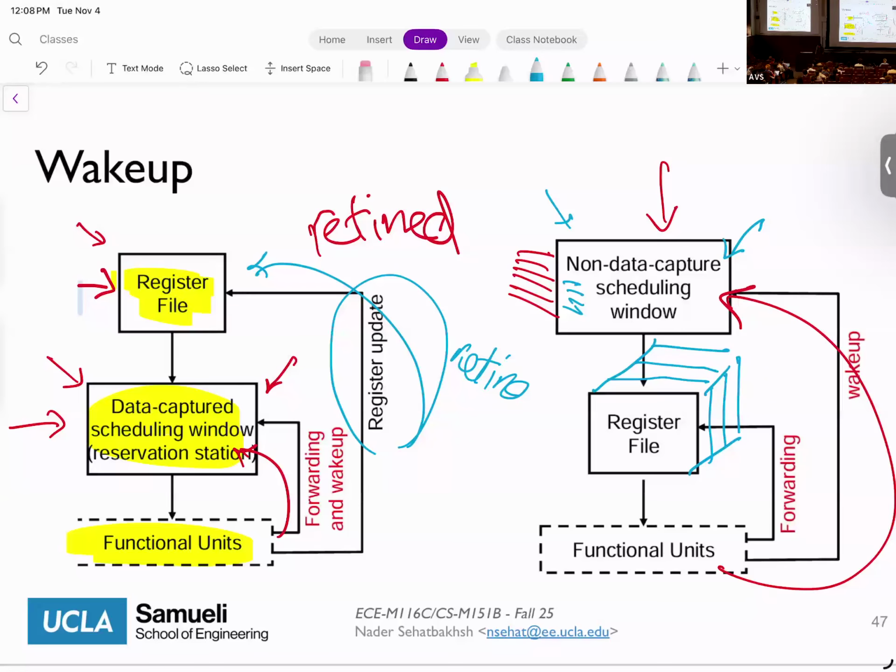Usually we have what we call a clean register file and dirty ones. The top one you can think of as clean, and all of these are dirty register files. When we are sure, then we write the dirty ones into the clean one. Think of these as checkpoints, and this one is the stable one, the one that doesn't have any speculation with it.